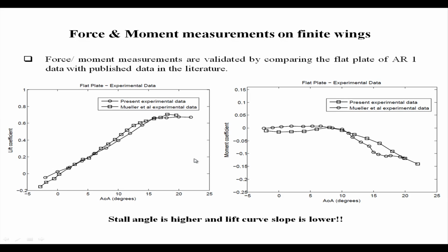Yeah, these are the force and moment measurements, as you can see. So, one thing that I have to again repeat over here is that earlier what you saw for the airfoils, there the lift was obtained by integrating pressure, if you remember, because of the kind of arrangement we had, but here we are going to measure it directly. So, it is both pressure and shear forces which are actually playing a role here. And as far as the normal force is concerned, it may not have so much significant effect as Dr. Satyanarayana has rightly pointed out, but yes, we see more impact on the axial part.